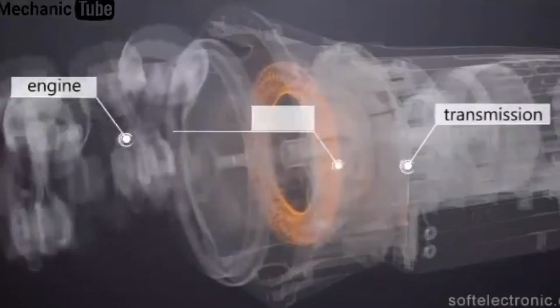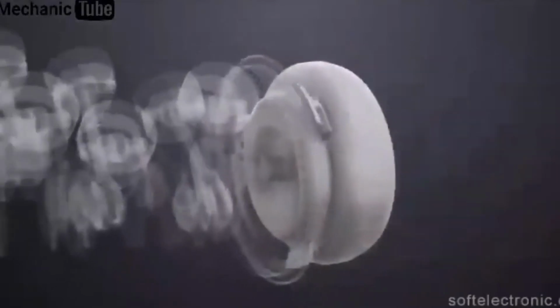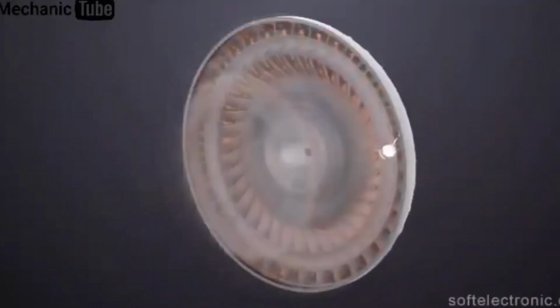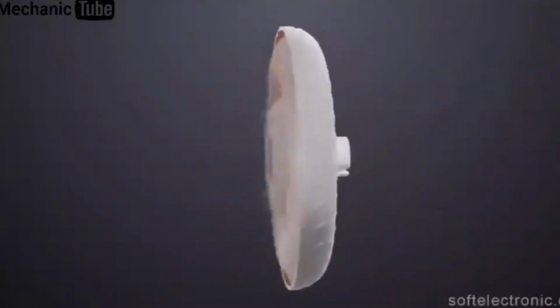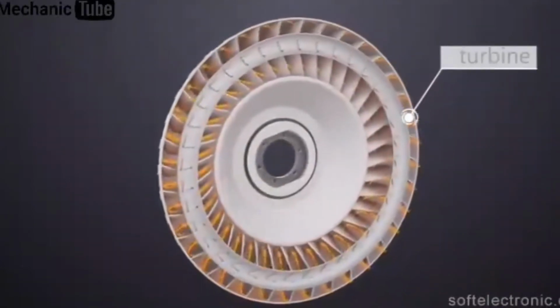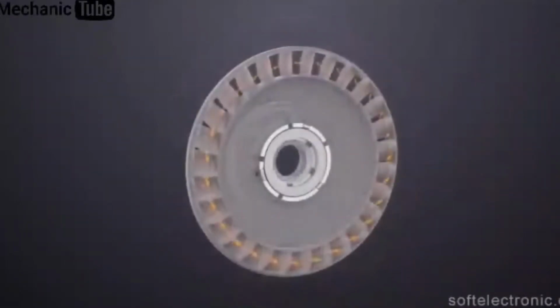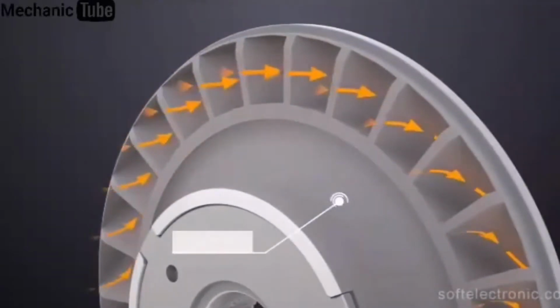In the torque converter mode, the connection between the transmission and the engine is made by pressure of the fluid flow. The way it works is as follows. The crankshaft in the engine transmits rotational motion to the torque converter. Driven by inertial forces, the fluid is directed to the outer part of the pump. From the form of the housing and the position of the blades, the fluid is then accelerated and guided into the turbine, which makes it spin. From there, the fluid passes through the stator, changing its direction to the optimum angle to the pump blades, and accelerates for a subsequent cycle.